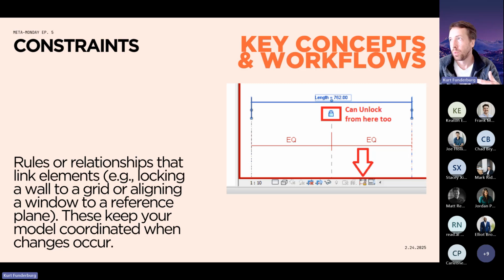Like we show, hey, here's the finished face of the siding, and then you're going to tack on your trim, and then your window sits behind that, but you're not seeing that there's a header there. You're just going to see that there's a void, and we know that there's a header there, so you'd have to go in and add your 2x6 header and orient it properly. You'd have to make sure that the plywood is the right hatch.